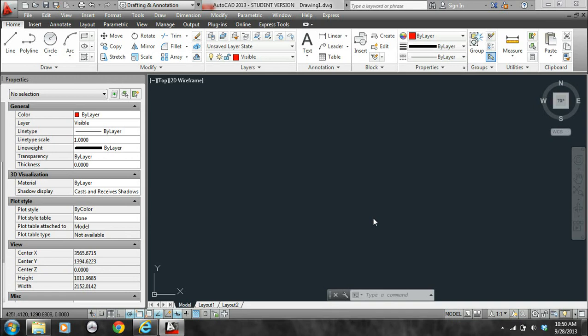There are a couple of telltale signs that let you know that it's a metric drawing, but the biggest one is that you see the word metric enclosed in a rectangle. All the dimensions you see are given in millimeters. So the template that you use needs to be different. Probably the biggest thing that you'll be able to tell is the title block.